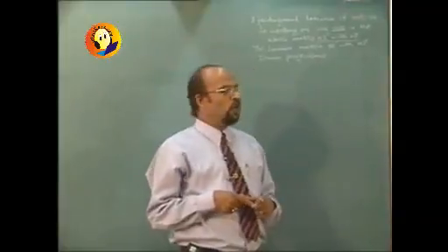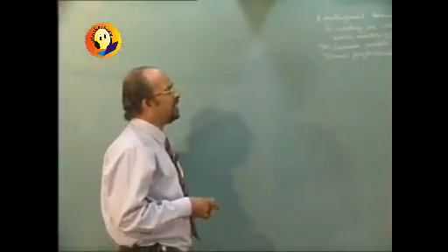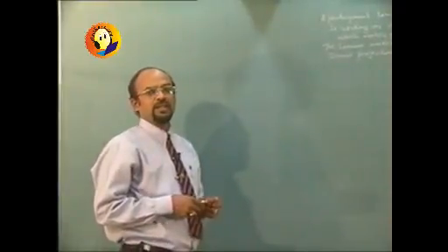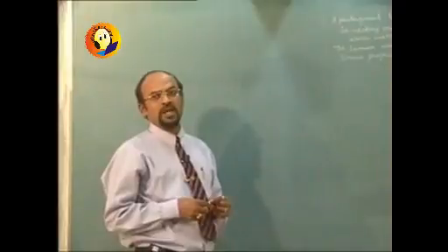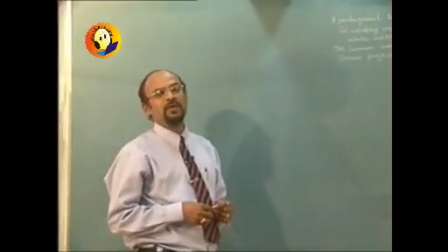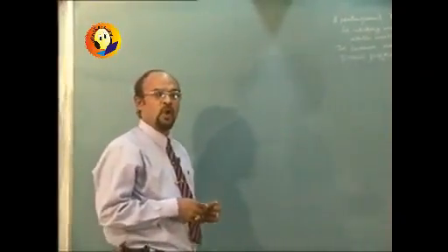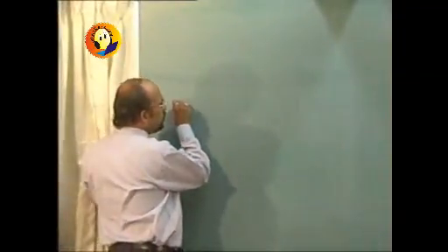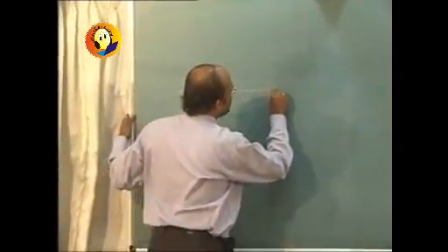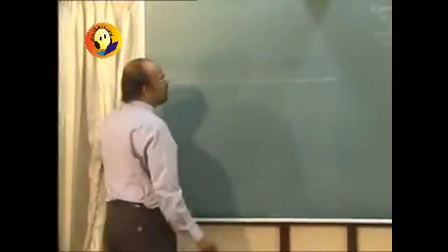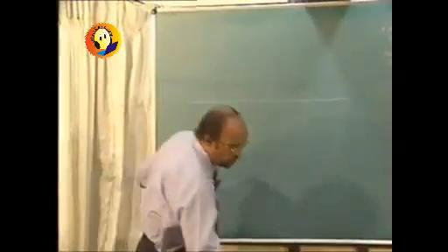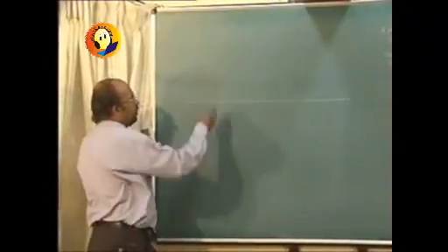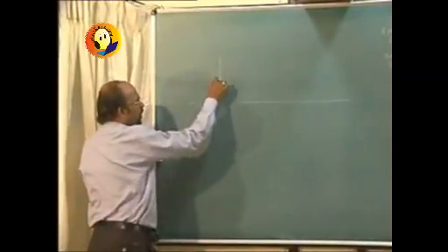So let us draw the pentagonal lamina. As the side is in HP, we will be keeping the lamina in horizontal plane, and then the top view will show us the pentagonal lamina in its true shape, and the front view will be simply a line view on XY as in case of the previous problem. So first we will start with XY line, and then we are required to draw the pentagon with its side perpendicular to XY.